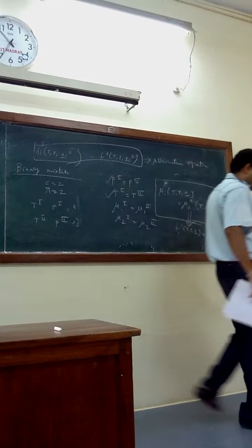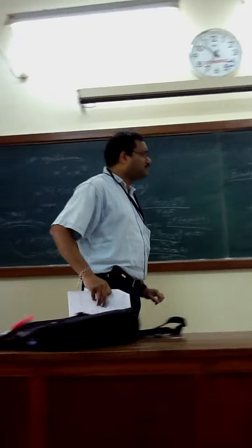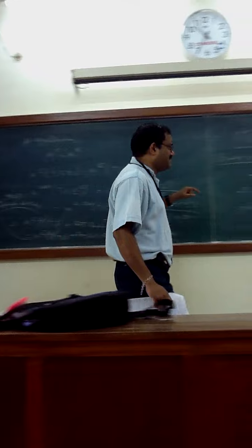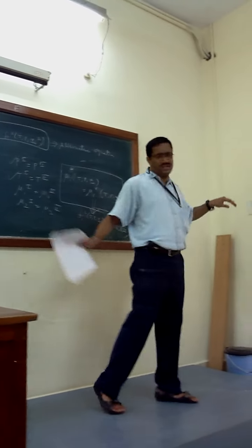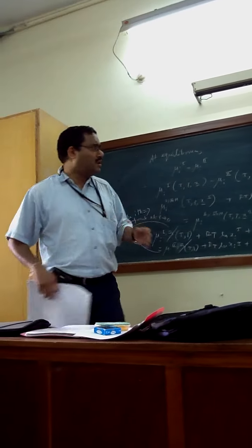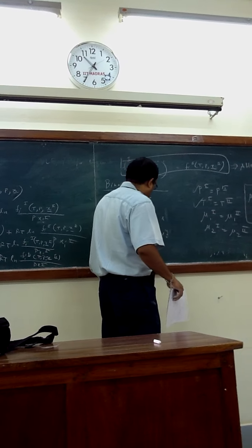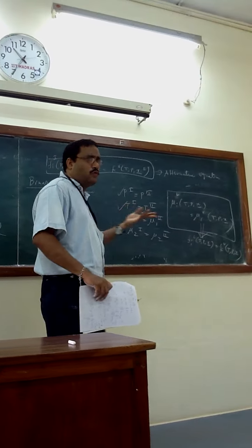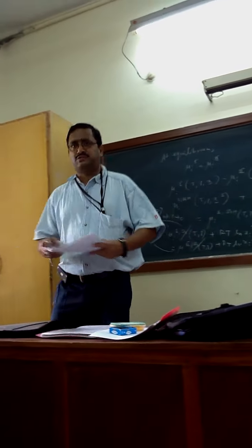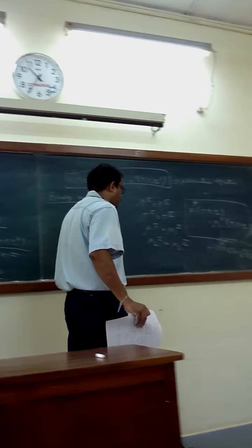So now the challenge is how to solve this. For a binary mixture it is okay. If you have a multi-component vapor liquid mixture, you need to solve this. It also says that the degree of freedom is 2. Either you can fix temperature and x, or pressure and y, whatever. You are free to choose 2 variables. We will discuss some numerical problems, as I have given you in problem set number 4. We will discuss how to use this concept and get all the problems solved.